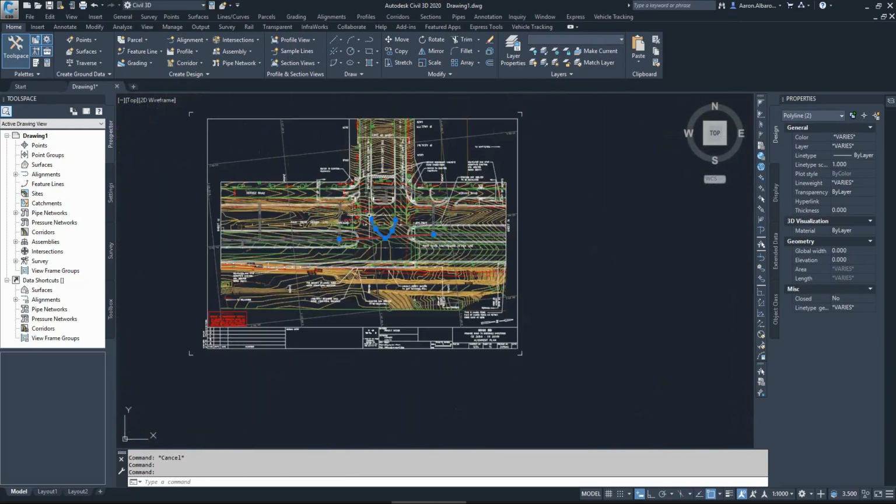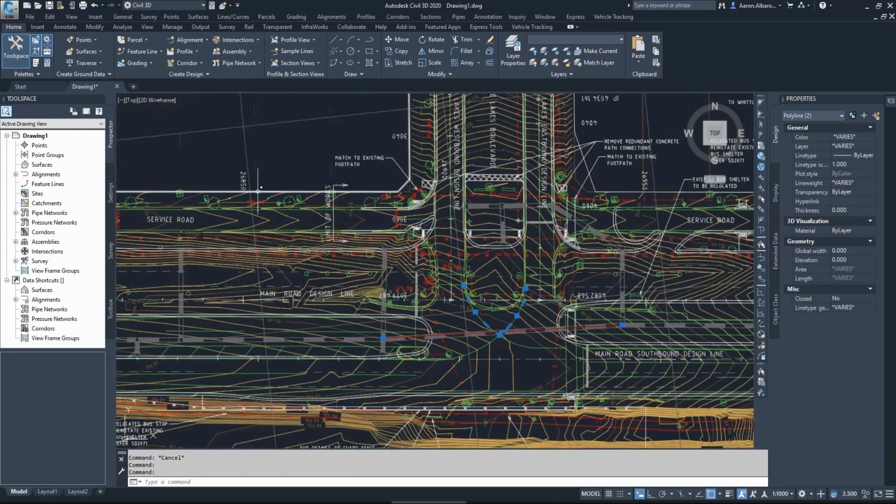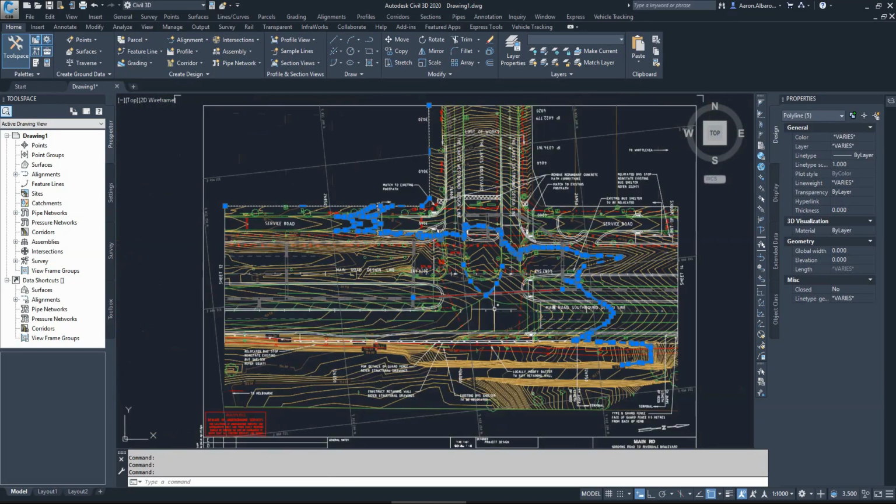First of all, as you can see, the PDF has now turned into lines and polylines, so you can work with them, which is a great feature. That will help you a lot down the track when you work with consulting offices. It will allow you to import PDF layouts from the architect or from anyone who did the previous stages of the design, so you can work with them in AutoCAD or Civil 3D.